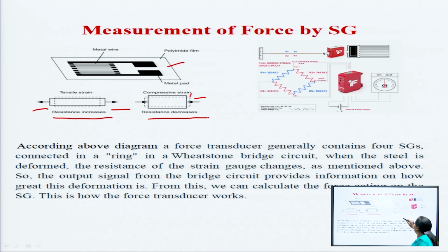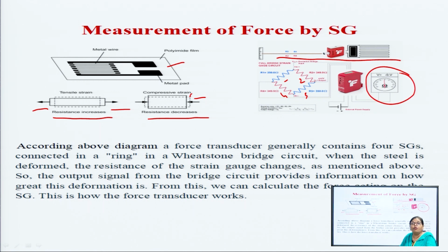You can see the industrial application, in bridge form. This is a single strain gauge. Here you can use 1, 2, 3, 4, and here I am mentioning the values, with the direct picture also shown. This is the strain gauge and this is the display device, which measures the force indirectly. The parameter we change is resistance, and that change in resistance is calculated or calibrated in terms of force. So we can measure with this help.